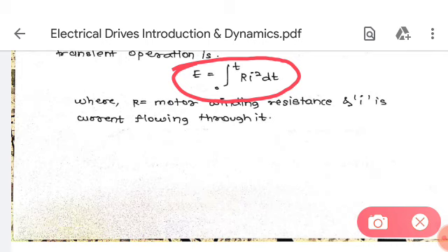So while selecting the machine, we have to study the duty cycle of the motor, meaning how the load is worked, whether it is started with some high current, whether there are many speed changes, and whether braking is done within a short time using the electrical braking method, or there are several speed reversals. All of those we have to take care of, and the energy lost in those operations has to be taken care of, and then we can calculate the motor power rating. That part we'll take afterwards, but for the sake of knowledge I'm telling this.